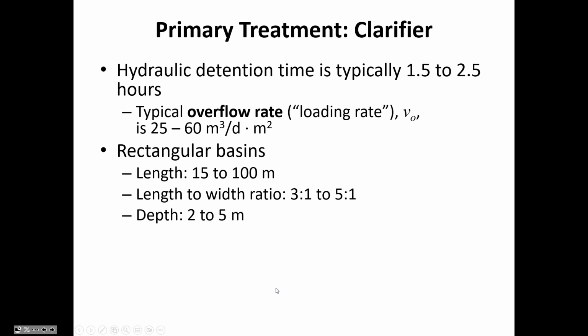There are the same kind of hydraulic loading rate parameters used for primary clarifiers in wastewater as were applied in clarifiers for drinking water. The overflow rate, sometimes called the loading rate, is the flow rate of the water divided by the area, the top view area of the settling basin. So basically the area over which the particles are settling down to rest on.